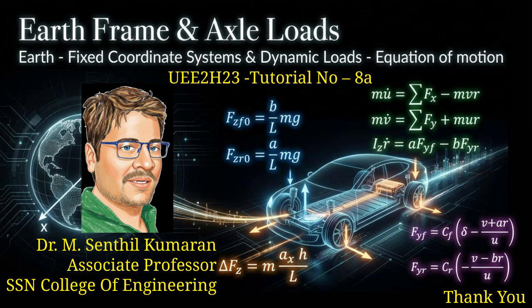First, define vehicle mass, inertia, geometry, tire stiffness, aero and rolling losses, drive force, initial velocities, yaw rate, yaw angle, position, and time step delta t equal to 0.1 seconds. For computing the initial response from 0 second to 0.1 second, compute drag, rolling resistance, longitudinal force, slip angles, tire forces, and accelerations. Update velocities, yaw, transform to earth frame and advance position. For computing the coupled dynamics from 0.1 second to 0.2 second, recalculate forces using non-zero lateral velocity and yaw rate. Include coupling terms r·Vy and r·Vx. Update accelerations, velocities, yaw, and position.